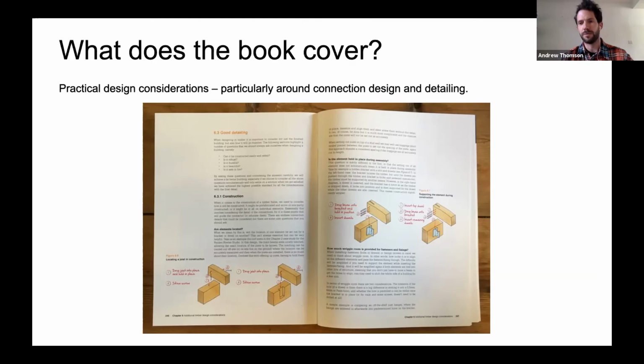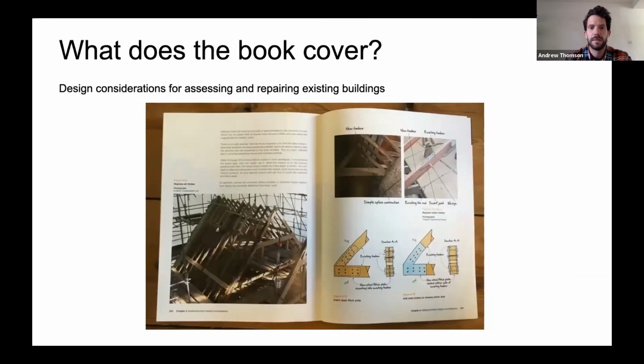That's the problem. You talk to anyone about anything, they say, oh, my bit should be at the start. But I do think this is a really valuable part of the book in terms of practical detailing of timber structures. So for example, in this picture, you can see the difference of a flitch plate connection. You can either drop a beam on, leave it hovering in space, try to drive dowels through, or you can notch the top of it and you've got a locating dowel. It's suddenly much easier and much quicker.